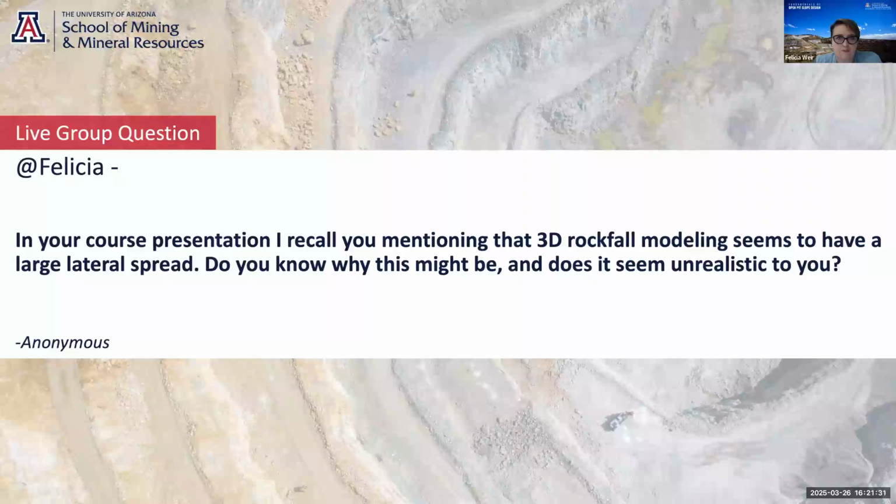One thing to keep in mind with the 3D rockfall modeling as well is that it's actually highly sensitive to the slope geometry that you're putting in. And if you put in a smooth design surface that has no roughness, you'll get quite different results compared to if you put in an as-built.